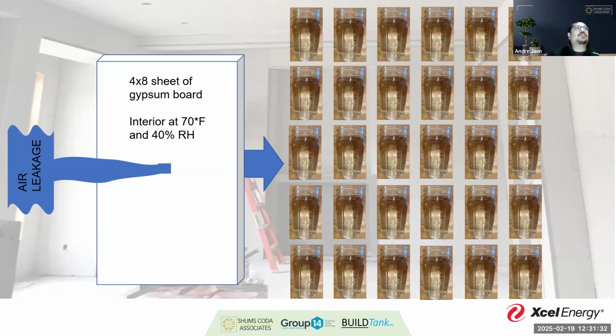But you think about all of your escutcheon plates for your sprinkler systems. You think about poorly cut outlet cuts, right? Those covers, I'm sure, they're plastic. I would venture to guess they're impermeable, but they don't have a perfect seal by any means. They're certainly not usually meant to, especially in places like residential construction. They don't have a gasket or anything behind them, so they're not getting a perfect seal. And you think about an inch is not that much space in a 4 by 8 sheet. And the amount of times that this can occur over a house can really start to lead to a significant amount of water intrusion.